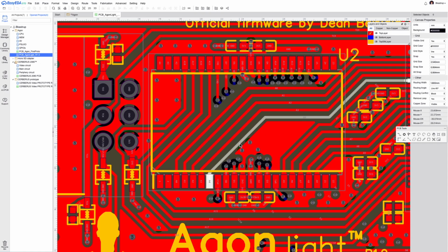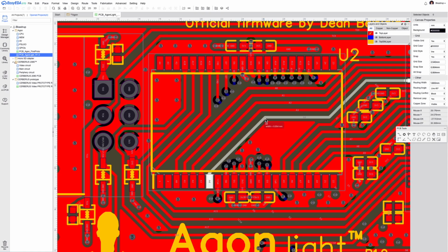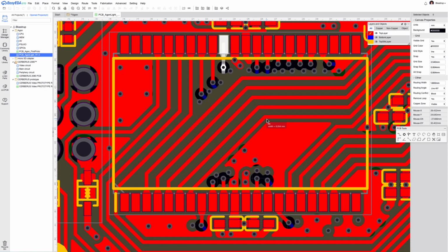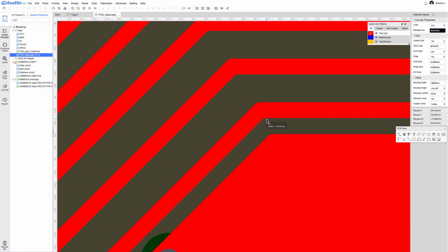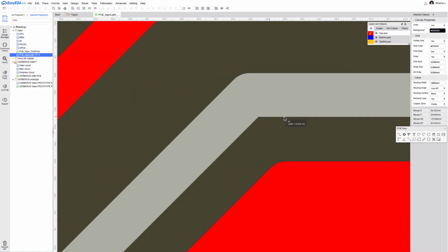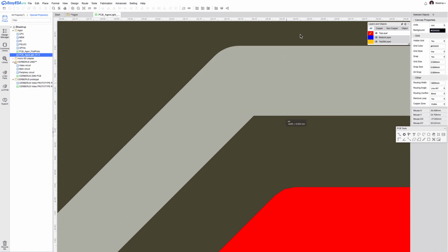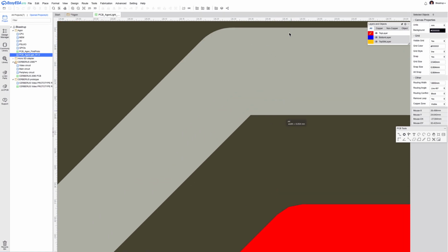And you also want to minimize the number of bends on the line. Like this is a bend, you want to keep the bends at 45 degrees because it reduces the impedance mismatch. If you get close to one of these bends, if you could measure very accurately the distance from here to here, this distance here, which is the width of the line, if you could measure this,